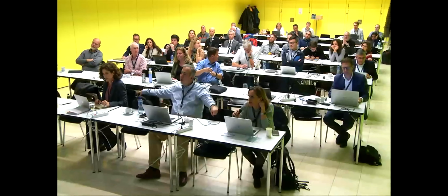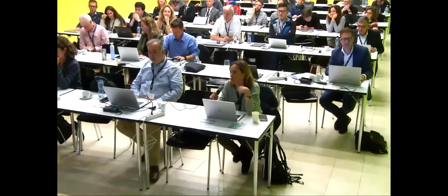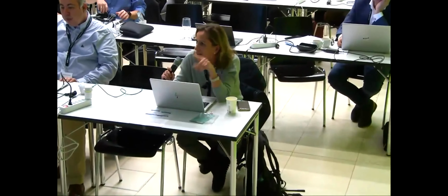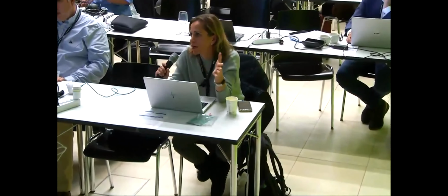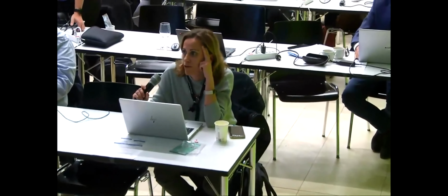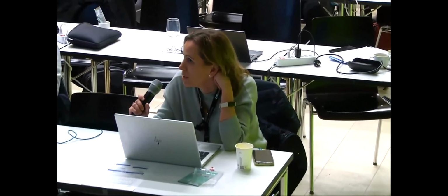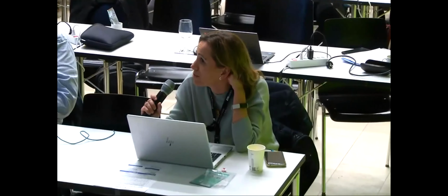Hi, Christelle, we have been working on similar things. On the numerical side, we have been doing analysis modeling saturated soil and liquefaction, and it does show one of your points: for dry soil there is no change in the frequency of the system. Well, for liquefaction, it can change the overall response quite dramatically and bring it, under certain conditions, to the frequency range that is important and leads to amplification. But as you said, it's very expensive computationally.